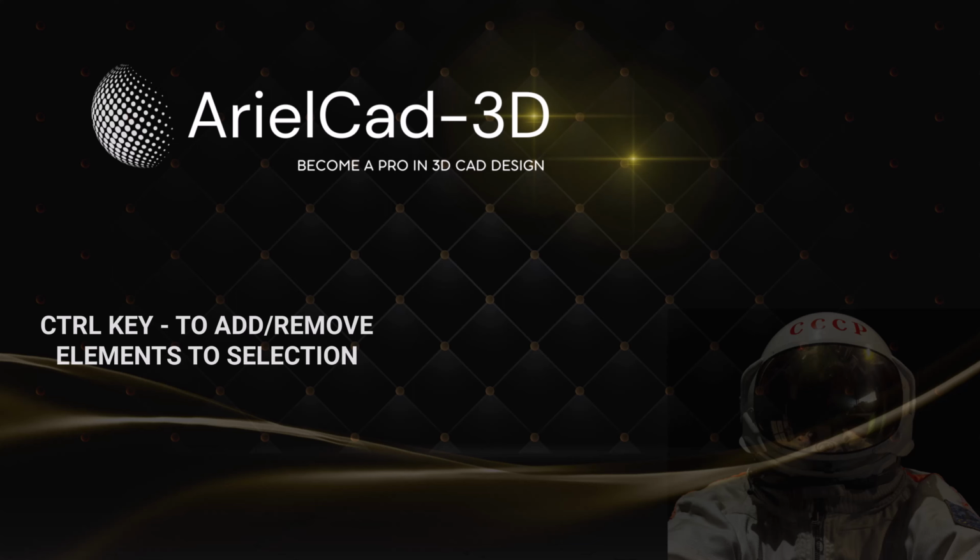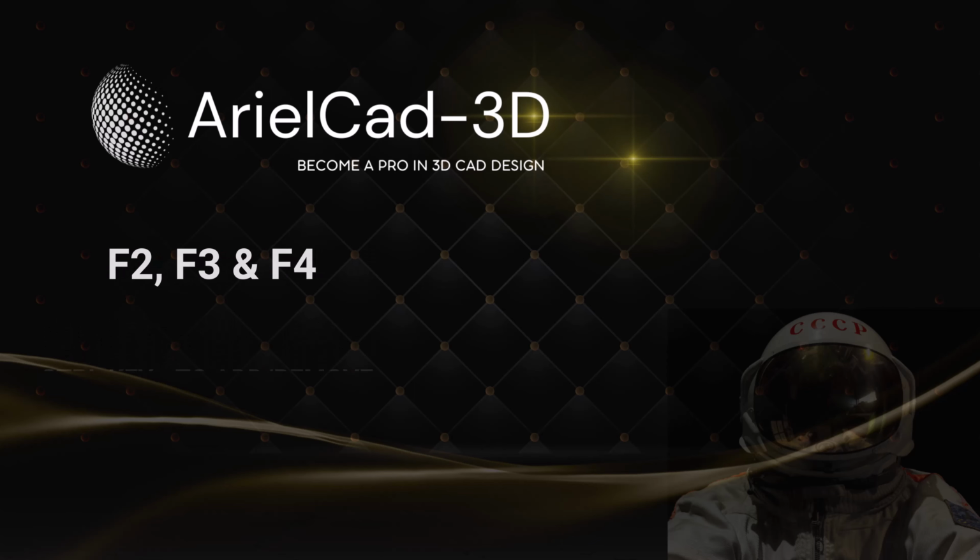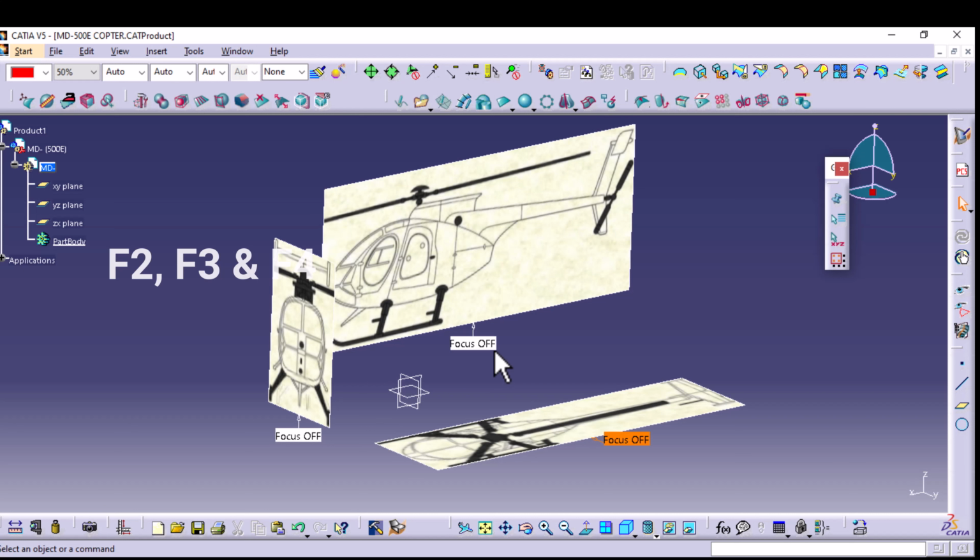Then we might use F2, F3, and F4. F2 is used to change between perspective and parallel views. F3 is to show or hide the specification tree. And lastly, F4 changes the view orientations instead of clicking this button right here when we are modeling. So don't stress over it. I'm going to be mentioning it when we get there. I just thought it's worth mentioning.